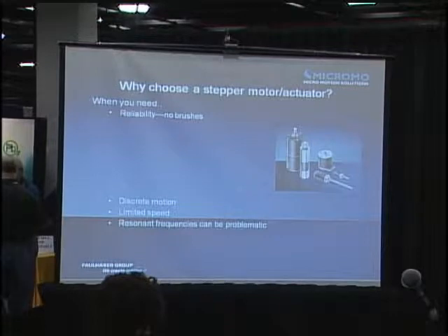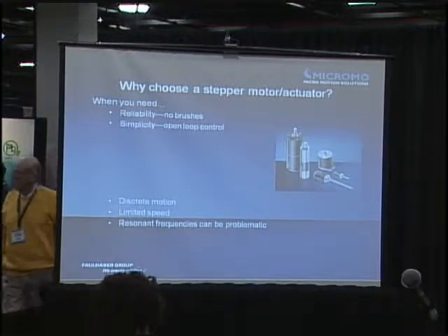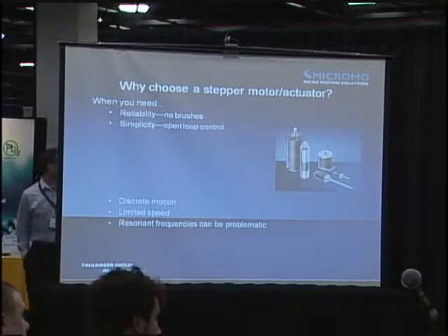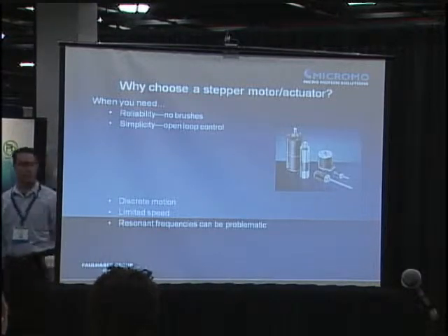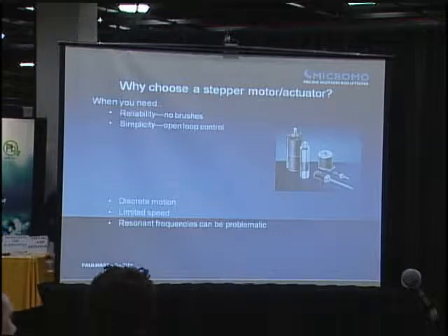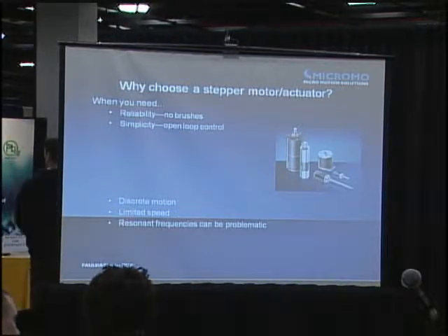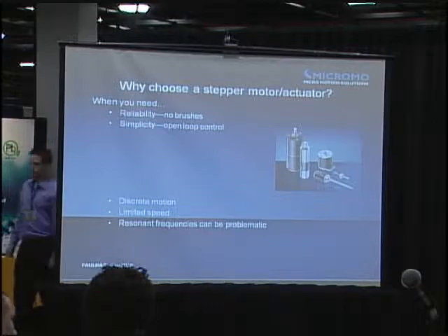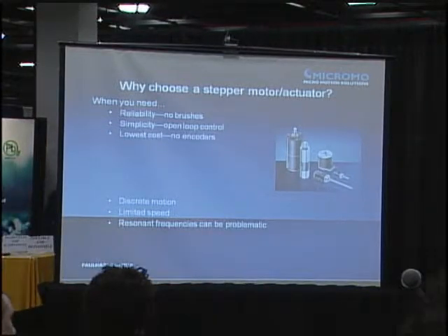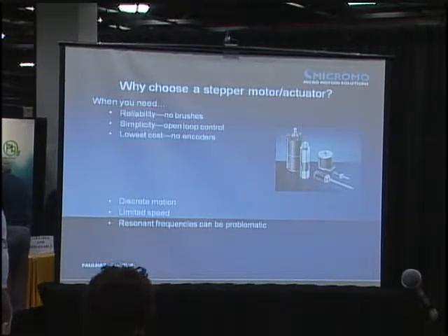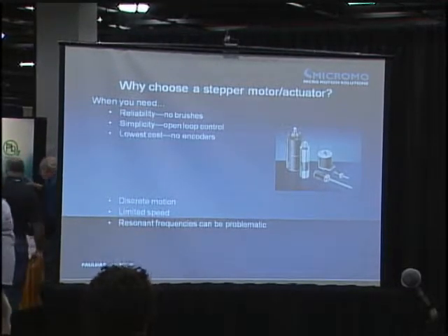they're essentially a brushless motor. They're easy to drive. That's the number one benefit probably for a stepper, is that most people like the simplicity of the drive. It's on the lines of a brushless motor, but not as much complication in the drive arrangement. They're lower cost as compared to a brushless where you're needing an encoder, where you don't have to have an encoder with a stepper motor.